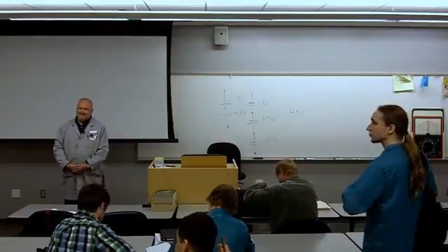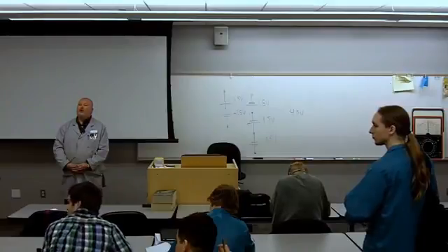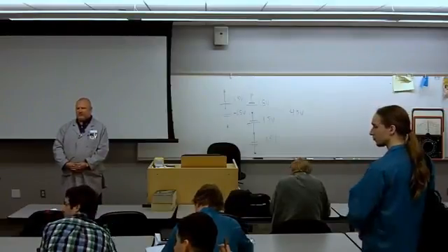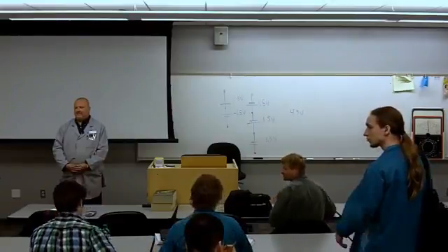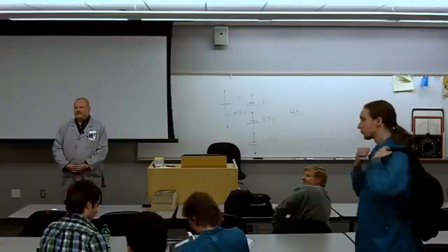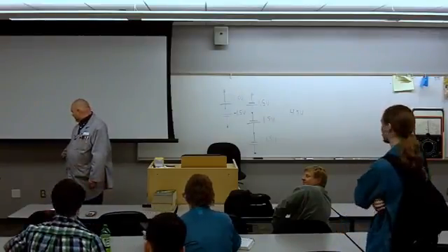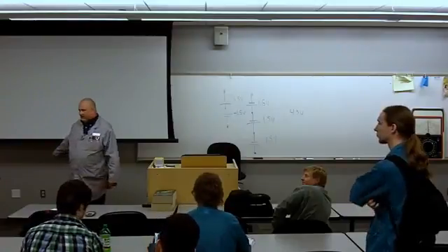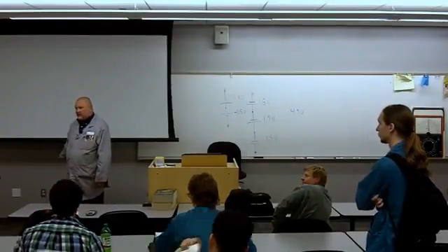So when you take a multimeter to test ground and it measures the material, what are you measuring it in reference to? I don't know, an electrical outlet, let's say. Okay. If I wanted to verify that this is a good ground, I could measure ground against my neutral.